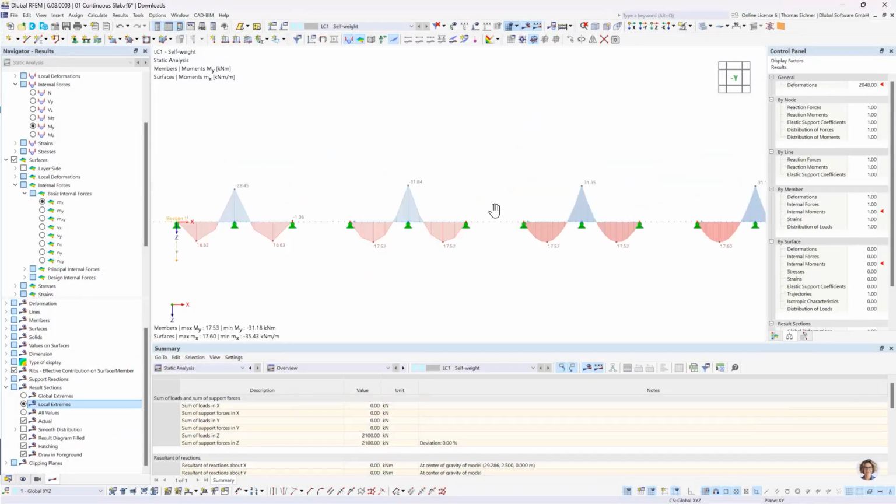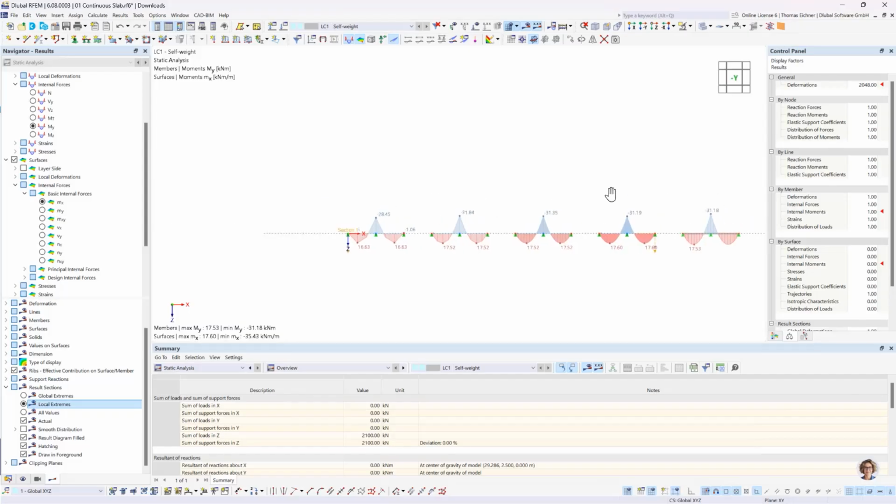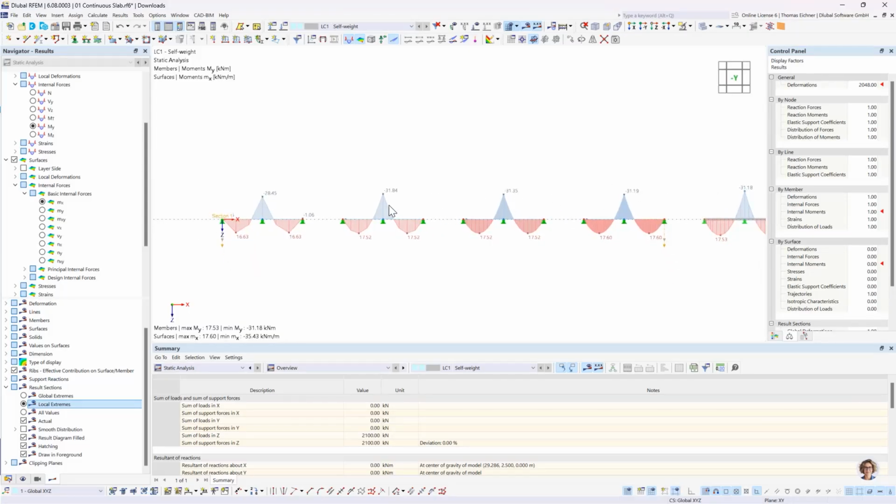So here, maybe we can look at that quite a bit better. Here this 28.45 versus the 31.818, yeah, almost 10%. That's not quite good. So that's the problem with this coarse mesh. We will lose exactness in the results.